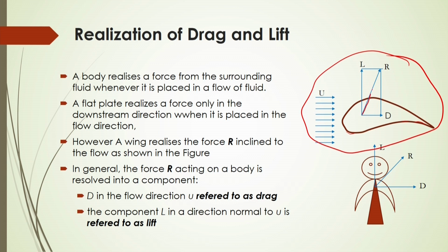In general, this force R acting on the body is resolved into components. The component in the flow direction, on the surface, will be considered as the drag force, and the component in the vertical direction, normal to the velocity, will be referred to as lift.